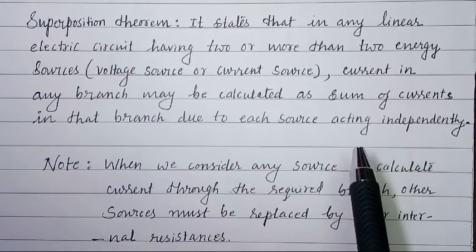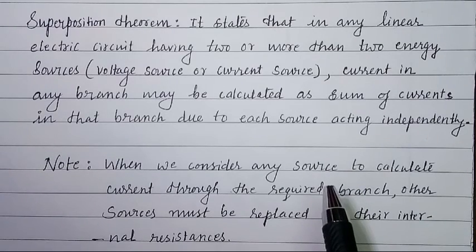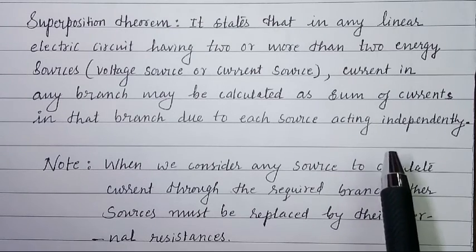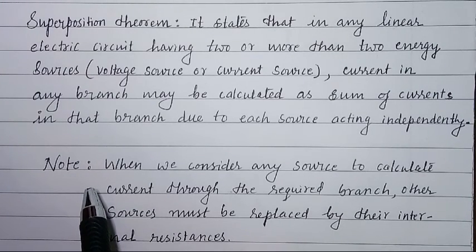So when we consider each source independently, then we have to replace all other sources by their internal resistances. So that is very important note here.